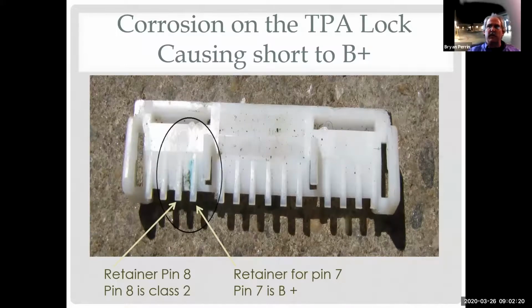A lot of times when rodents eat connectors or eat the wires off connectors, they don't leave anything. And some manufacturers only sell it as a whole harness. So it's $700 for a new harness plus about 6 hours labor, so you're talking $1,500 to a customer. Or you pull it apart, pull the pin out, get a little bit of wire and start connecting things real close to the pin. I've had to do that a lot of times, and I've never had it cause an issue.